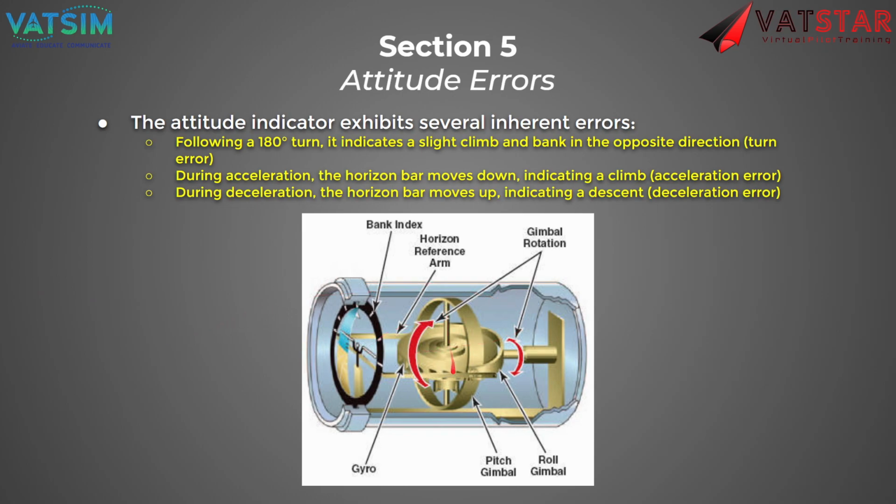So here on this vertical axis, you have the gyroscope spinning around and around. Now, as you rotate, think of it as rotating around this gyroscope. This gyroscope, because it's spinning, is always pointing basically up or down. This vertical axis will constantly stay pointed either to the ground or to the sky. So it's basically a perfect vertical line at all times, no matter which way the airplane's oriented. Now, that can get screwed up if you're doing aerobatic maneuvers. No gyroscope is perfect. It does fade over time in its accuracy.